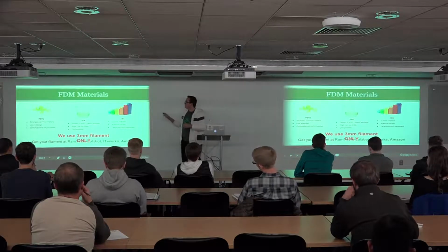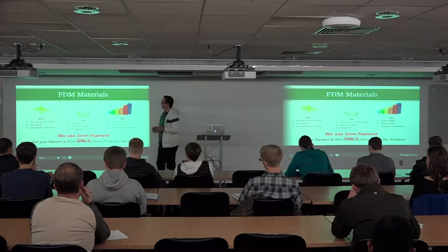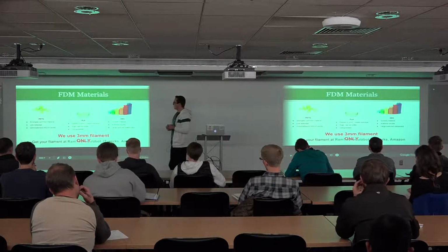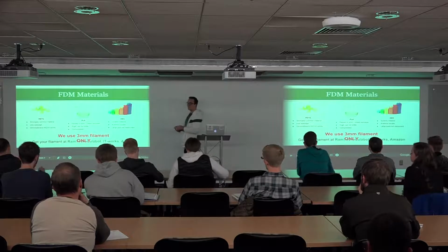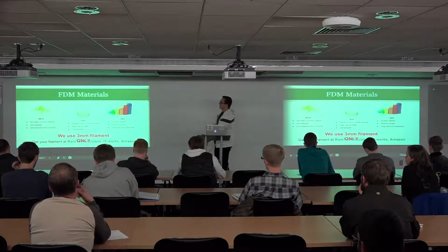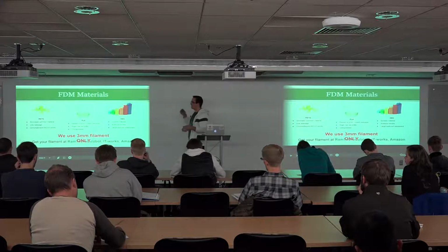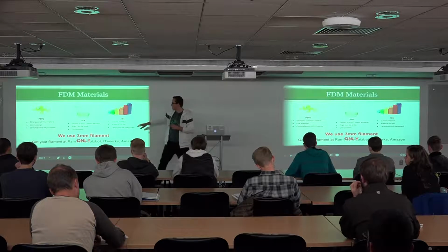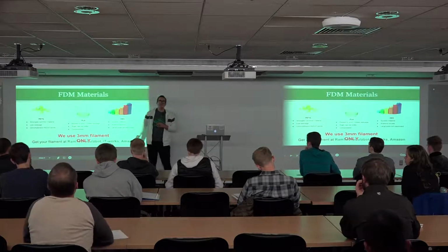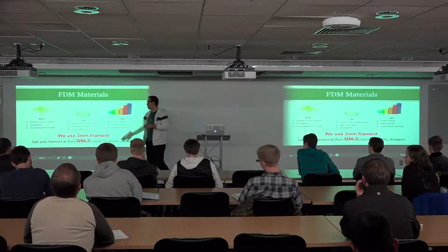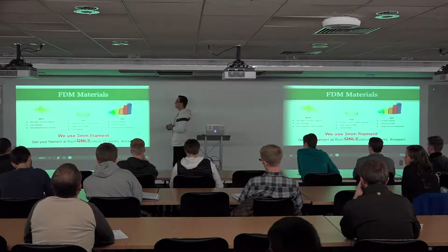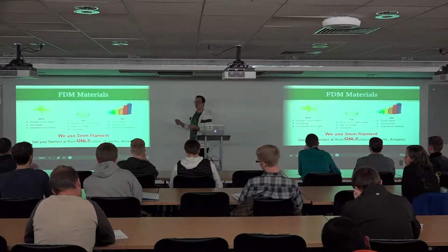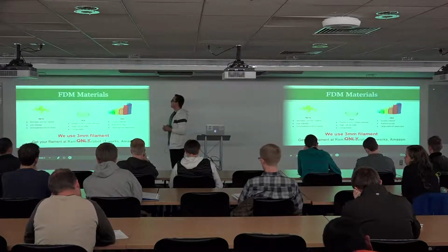Okay, so you might be more interested in FDM materials to get started. Interesting formatting there. That hopefully gets the info across, and I think that is one of the questions on your sheet. We made it big and we put it on the quiz because a lot of people ask us. In the industry, 1.75 filament is usually more popular, but all the printers that we have use 3 millimeters, and it should be about the same cost. But anyways, we just wanted you to know so you don't show up with 1.75 and go, hey, wait a second, which printer do I use?